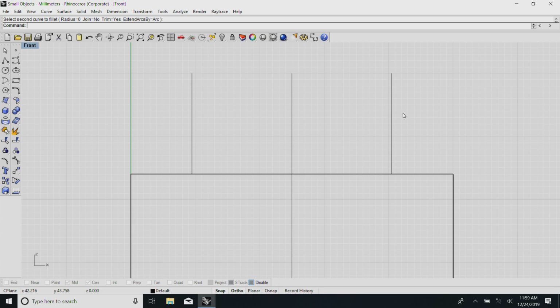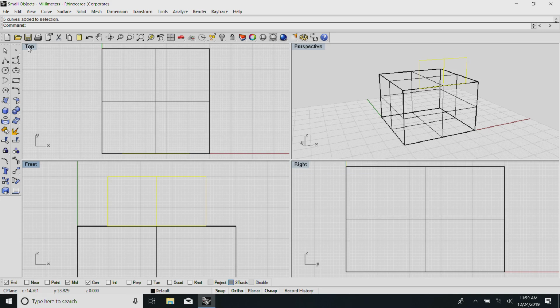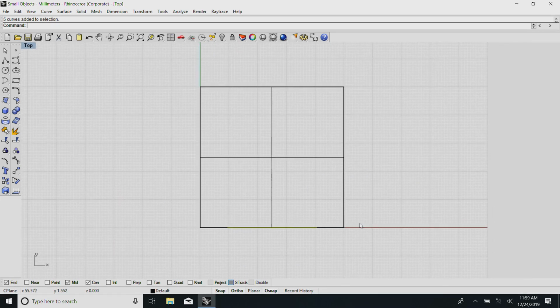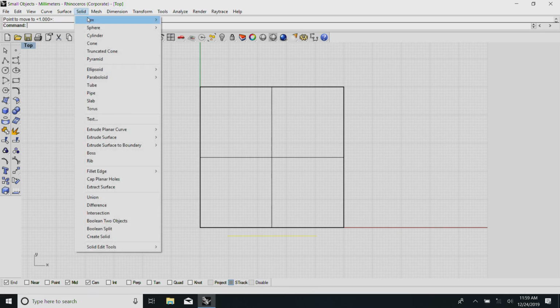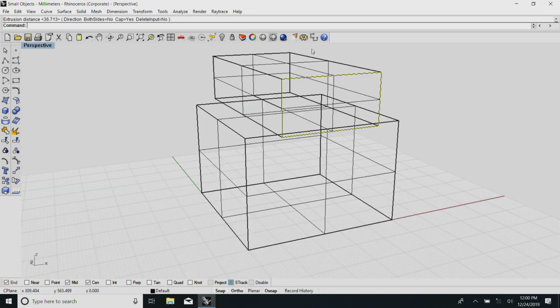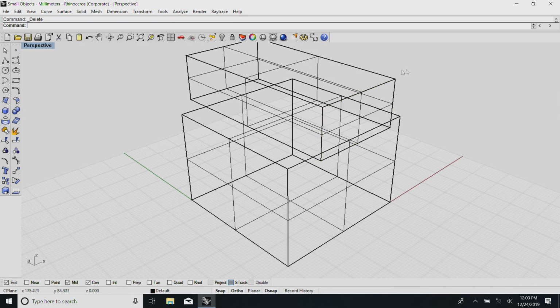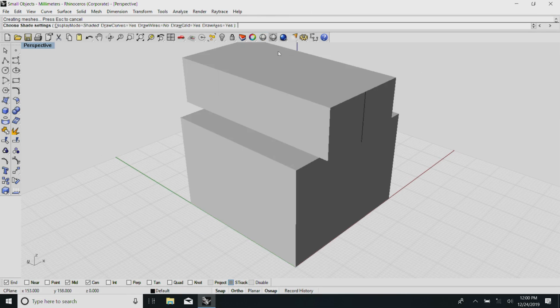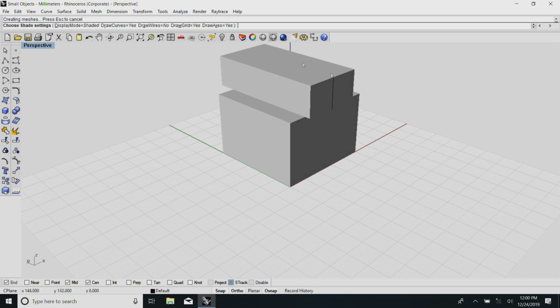Now, I try to create, you see here, if you see top to bottom, it is more than 10 millimeters, something which is required like this, and then after that I try to create this whole thing as a rectangle. Now, if I go to the other view, I will notice that it is sitting here. Using this, what I managed to make is one more intersecting solid with which I can remove the material.